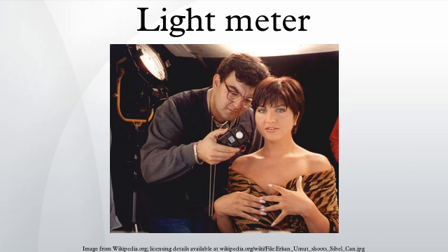Selenium sensors generate enough voltage for direct connection to a meter. They need no battery to operate, and this made them very convenient in completely mechanical cameras. Selenium sensors, however, cannot measure low light accurately and are altogether unable to measure very low light, such as candlelight, moonlight, starlight, etc. Silicon sensors need an amplification circuit and require a power source such as batteries to operate.